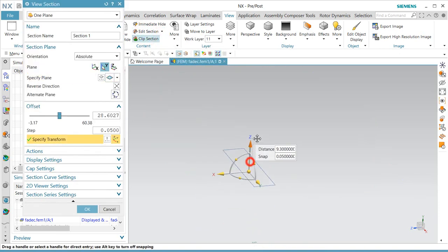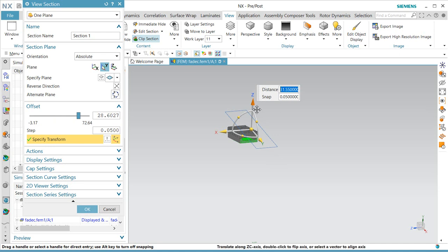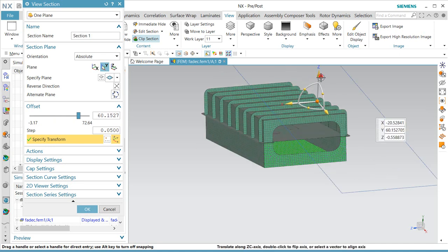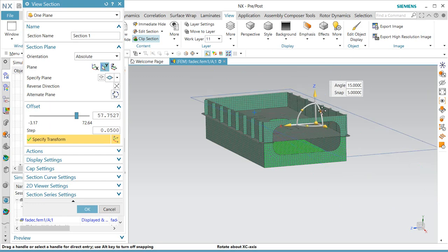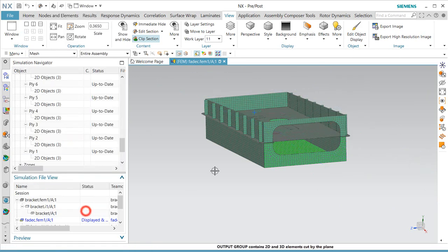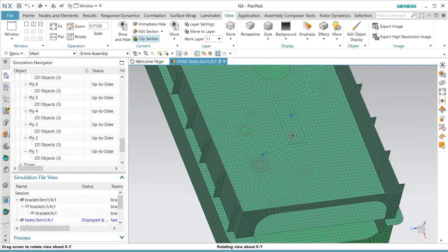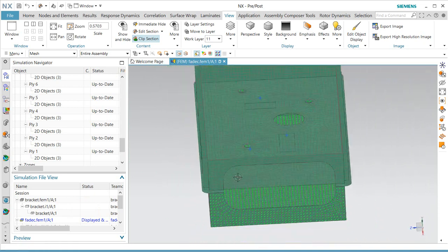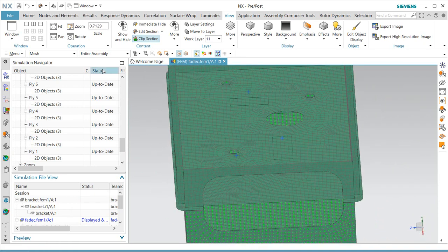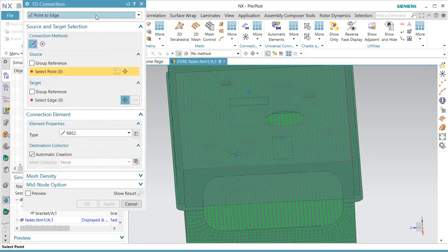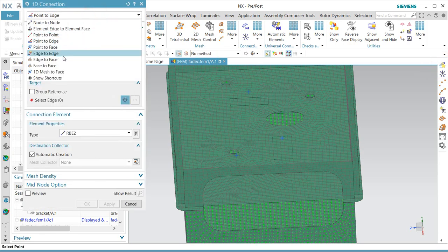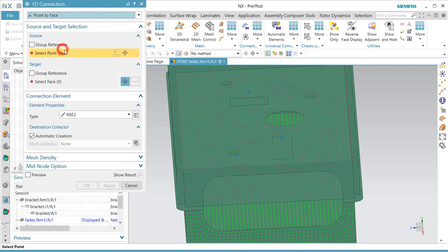Now we have one more thing to do, which is to connect the components that we had defined with concentrated masses above the board and connect those onto the board. I'll go ahead and chop off the top of the box with a section view so we can see inside a little bit better what's going on. And here I'll use the predictive toolbar to create my 1D connection.